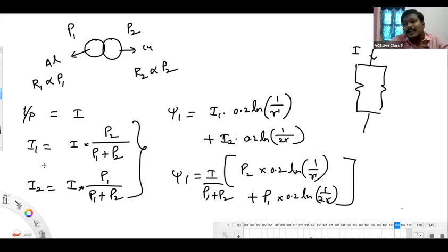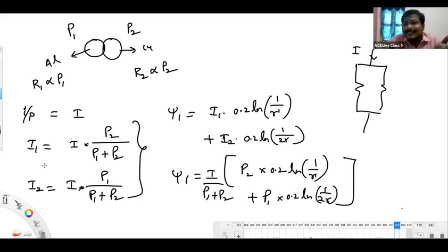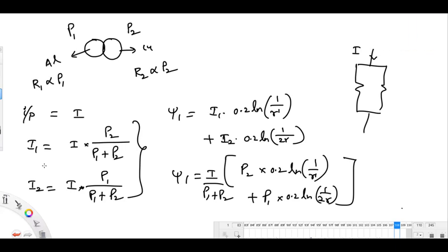Convention. Not only that, Kushal, our older power system engineers designed the analysis in the power domain, not in the energy domain. If they had analyzed this in the energy domain, I would not have an issue of reactive power at all, because when summing up, it will be cancelled out. For one cycle, reactive energy will be cancelled out, and the resultant is the net energy. So if you work in the energy domain, there is no concept of reactive power at all.